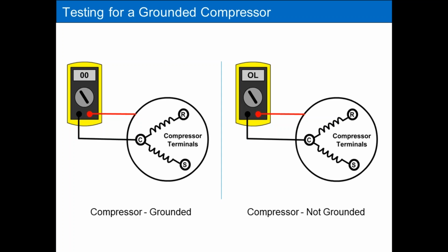from any terminal to ground using your standard ohmmeter that's not reading millions of ohms. Get away from the million ohm meters, because you may read millions of ohms from any terminal to ground. That doesn't mean it's shorted. It's just a high resistance value. So get away from these million ohm meters when you're doing these tests. They really can cause you some grief.